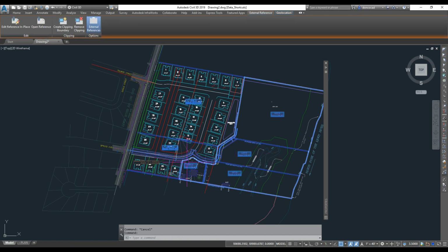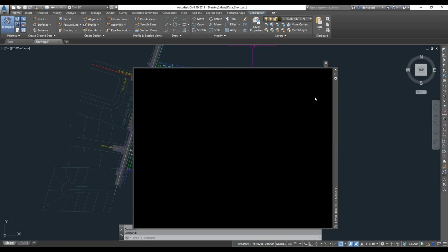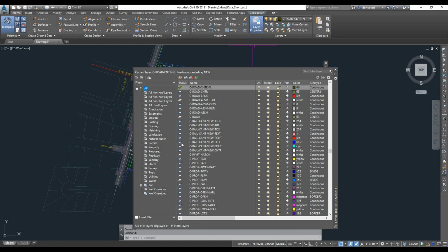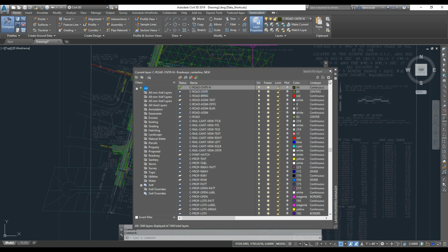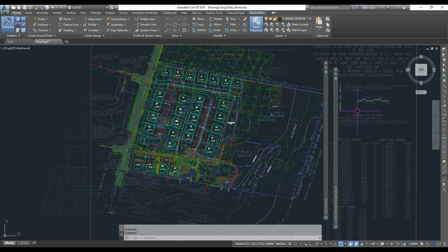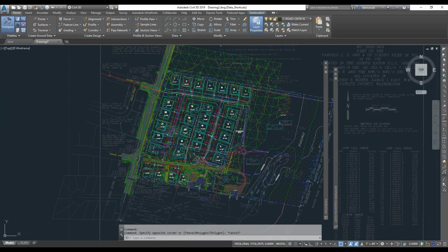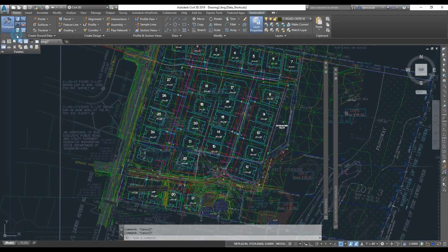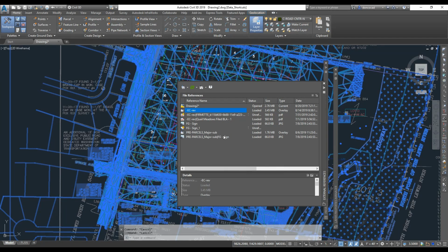Okay, starting out, this was two phases of a development. There were 5 lots there on the river in the existing house lot. I pulled this drawing in from the planning from the engineer that had provided it. Added it into my template for the layer filters, XREF'd in the PDF survey, shows the green tin outline. Surface does not cover the extents of the property. Let's see, these are my XREFs, existing conditions.